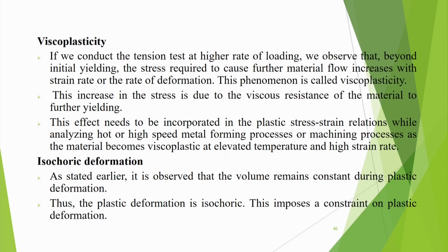So, at high strain rate, naturally the material will appear to be stronger. This dependence of the flow stress on the strain rate, or the rate of deformation, is known as viscoplasticity. We say the material is viscoplastic. The increase in the stress is due to the viscous resistance of the material to further yielding.